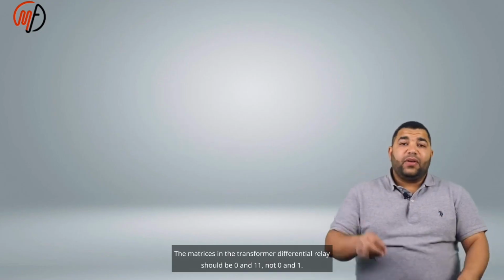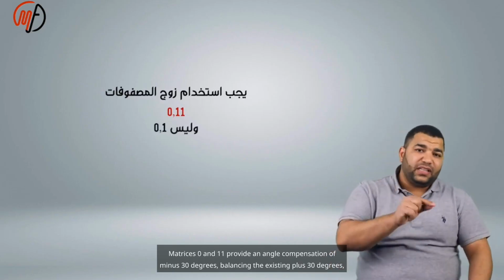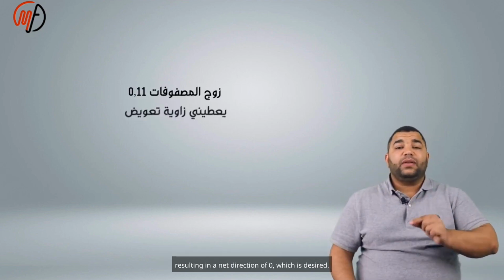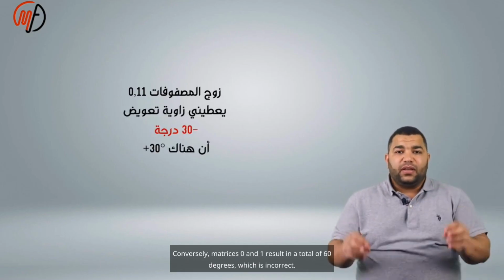The matrices in the transformer differential relay should be 0 and 11, not 0 and 1. Matrices 0 and 11 provide an angle compensation of minus 30 degrees, balancing the existing plus 30 degrees, resulting in a net angle of 0, which is desired. Conversely, matrices 0 and 1 result in a total of 60 degrees, which is incorrect.